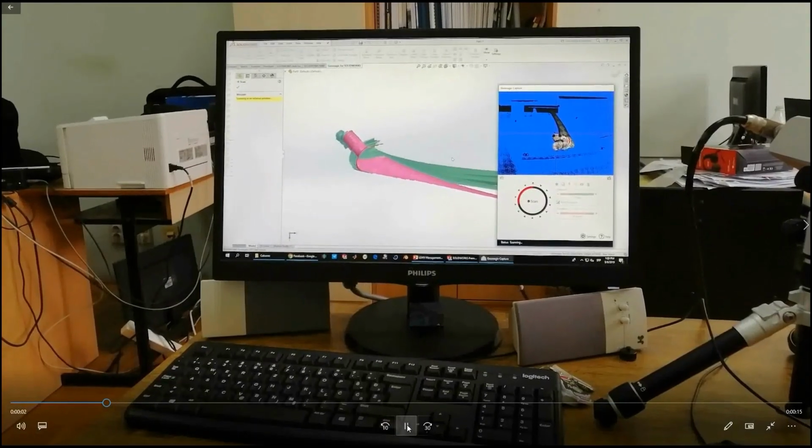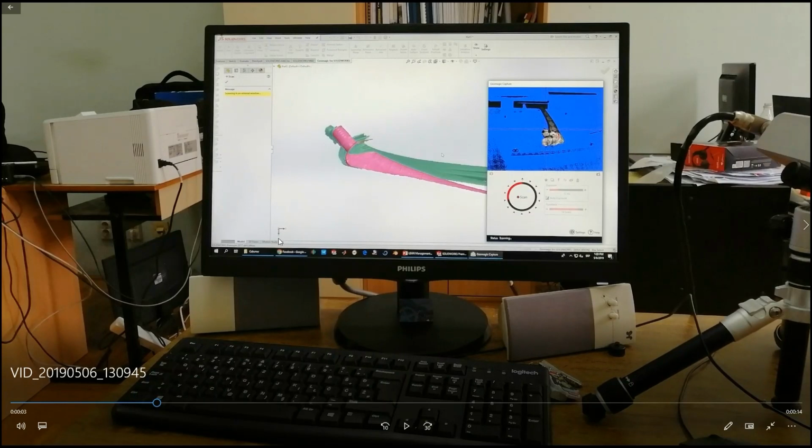What you see here on my computer are the slices which the 3D scanner makes. This is the first window defining our process in 3D scanning. I have to define the exposure of light, how long it will be, and it will define the resolution of our 3D scan.